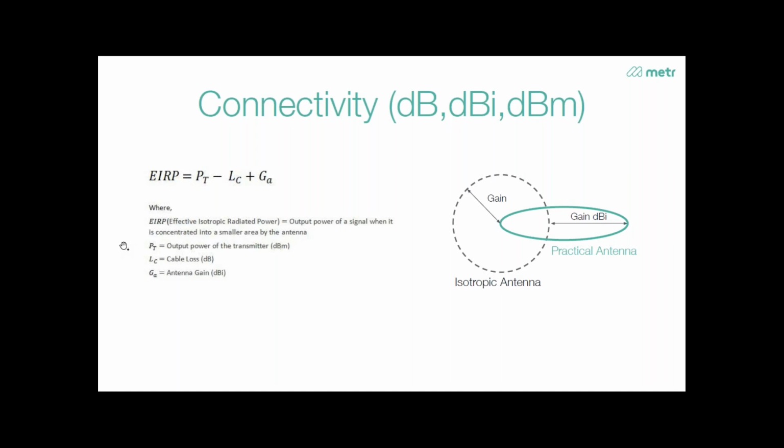What you can see on the right-hand side is, imagine if your antenna were a perfect sphere, right? With 0 dB, that's the reference that you're measuring against. And of course, because your antenna is always slightly directed, you get some gain because you bundle, you focus a bit in a certain area. Most of them don't have a signal on top. It's not a perfect sphere, right? It's more like a donut, is that a good description? I'm not sure, but you know what I mean, that at the top there's no real reception.